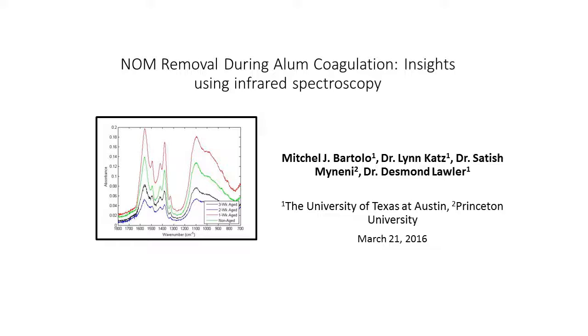Would this ever make sense, or would you always go to the tank aeration? I think there are places for both. In that particular case, you've got a tank hot spot. If it holds water in a hot spot, you're going to treat that tank if it's reasonable to do so, rather than running the water out of the tank through a membrane. Through the tank, you might have to treat several hundred gallons at once. It's hard to split off. Hydraulically, maybe you're pumping 10 or 15 GPM in a small system.